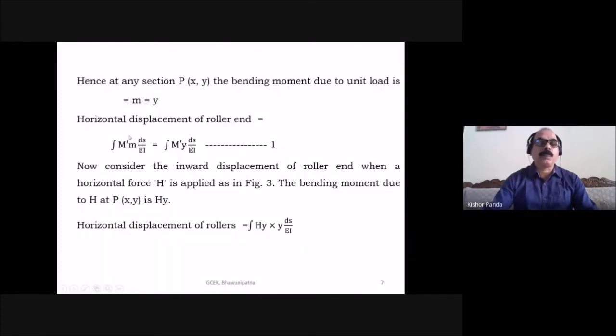But you know the horizontal displacement of the roller end by the unit load method: the integration of capital M dash into small m into ds by EI.